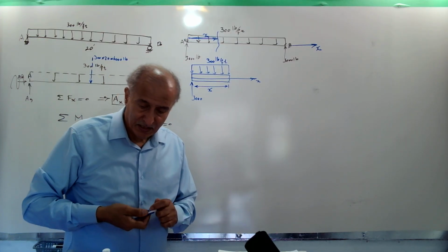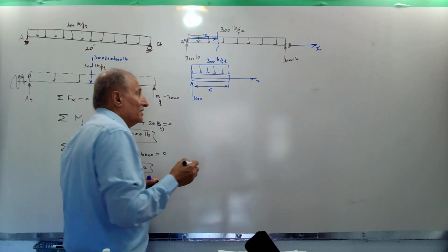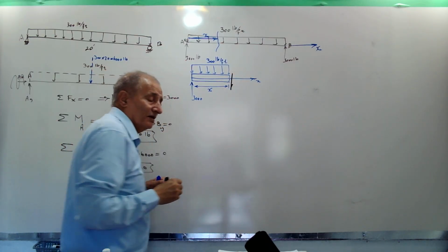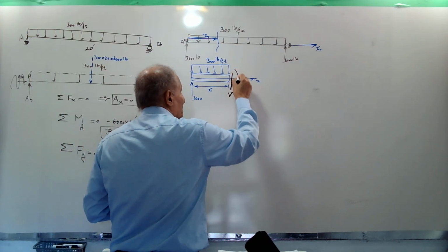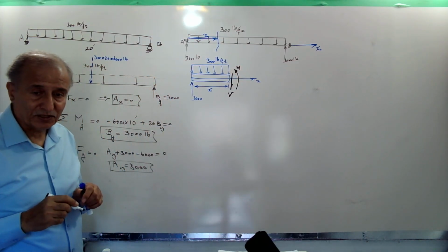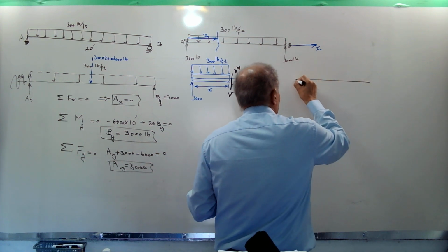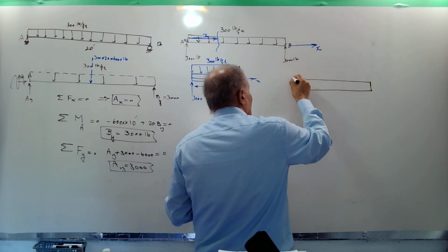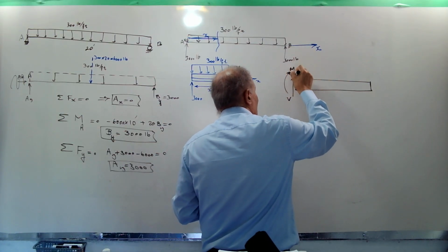And because we cut the beam, at the internal reactions in the beam, you know there is a shear force of V inside the beam, and there is a bending moment counterclockwise inside the beam. If you consider the right side portion, according to the convention, actually V should be upward, bending moment should be clockwise.